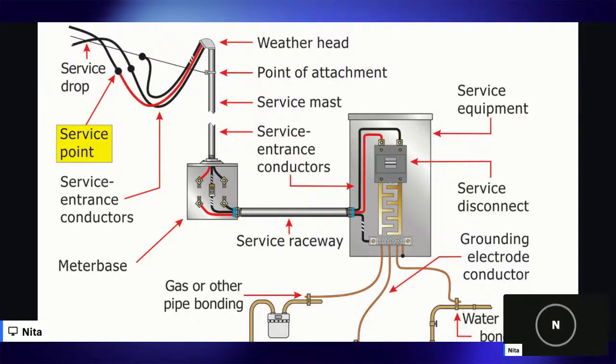These are called your service drop conductors. It's going to be 2 hot wires and then 1 neutral. The neutral basically recycles the electricity. Or it serves as a what? Oh, like a return? Correct. A return path.